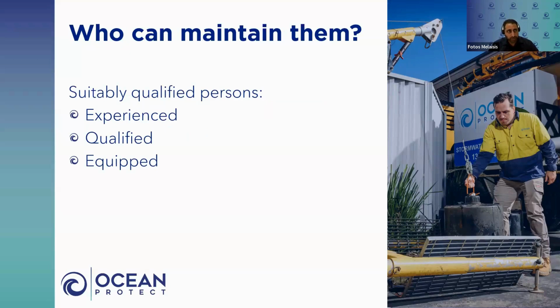And then you can move into some of the more general annual type frequencies of removal and disposal of litter and debris and sediment. And then you've got more major components, so comprehensive cleaning, whether it be replacement of filters, flow testing, these type of items that quantify the actual performance of the treatment asset. And finally, some structural repairs or potential rebuilds depending on the extent of the actual device.